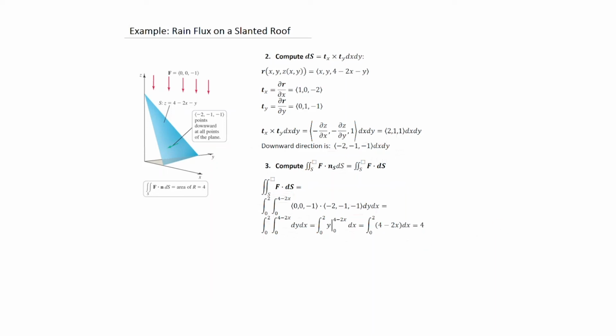All right, so this would be a mass flux. Mass flux would be in terms of kilograms per second per meter squared. That's the amount of rain that's hitting the surface, the flux density, and we would be computing it over the full surface area. So we'd be talking about kilograms per second of rain that has to be removed by the gutter system.